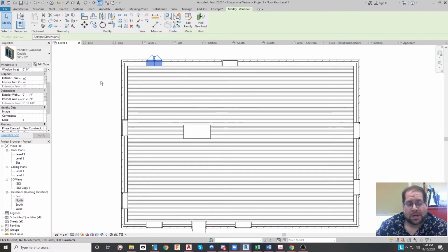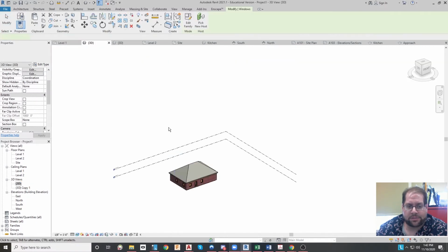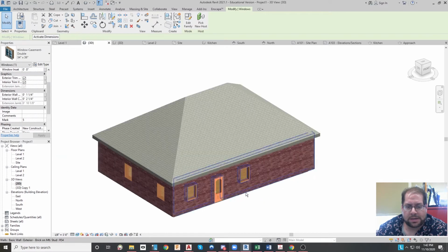And also those object types, once you edit them, can be repeated in several ways. So it's a really powerful particular thing. Right underneath it, you'll see the project browser. Some people tend to be confused and think that what this is showing you are different files, but that is not the case. In Revit, there's only one file active at a time, more or less. It's an RVT file, and the RVT file contains everything that's in the model. So the building that you have, whether you're looking at it in 3D or 2D, is the same file.